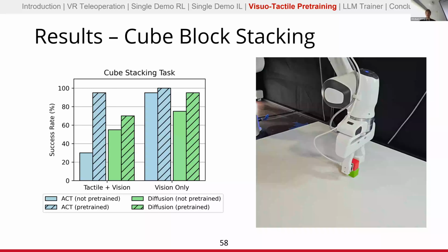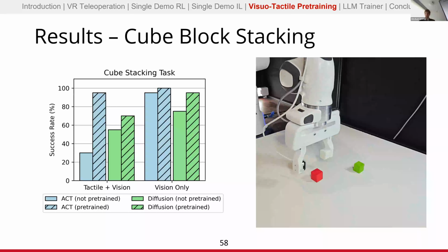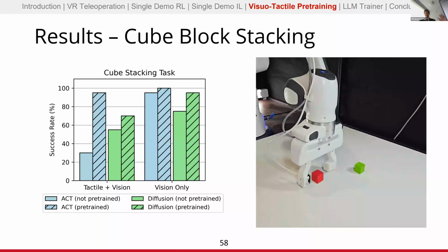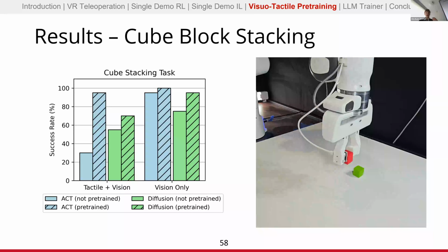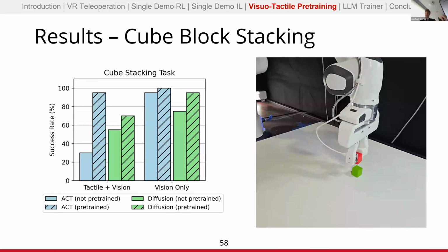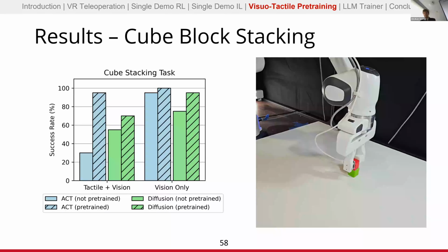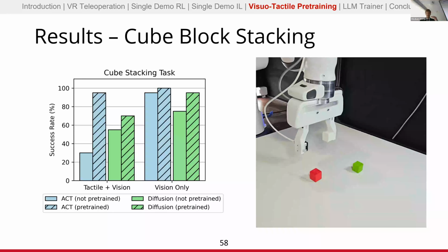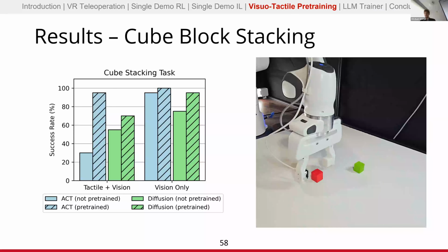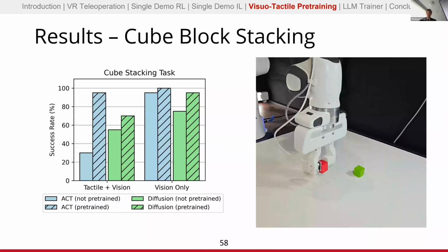Also, if the lighting changes significantly for a run, or the object is in a weird pose, or the robot's impedance controller has some error, that's just standard. Another really common thing, especially for ACT, is that if it ever gets into a state where its action after ensembling is to not move, then it's still in that state, with the exact same observation and exact same output, and you get stuck in this loop of my action is to not move, so therefore I stay in my current state, so therefore my action is to not move, and you just stand still for the rest of the demonstration.